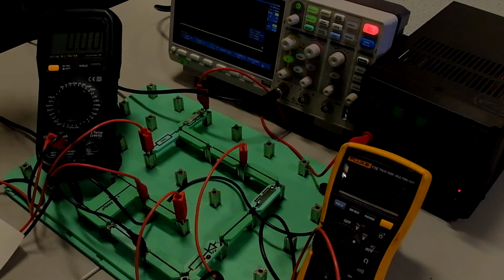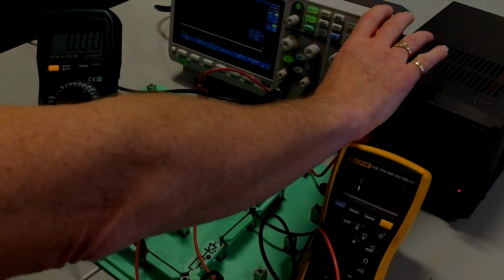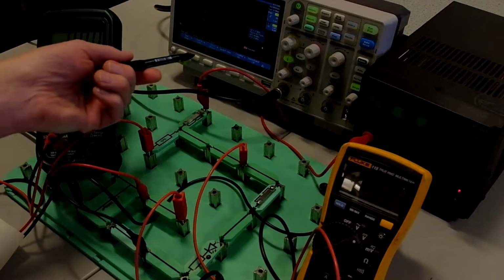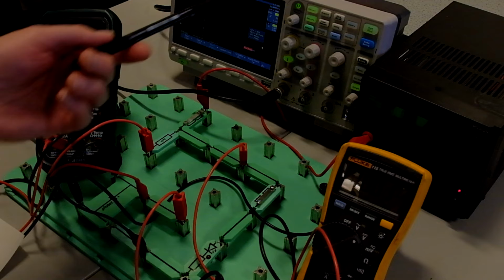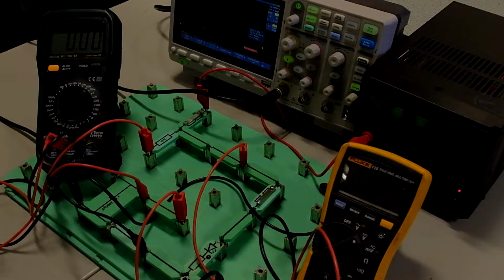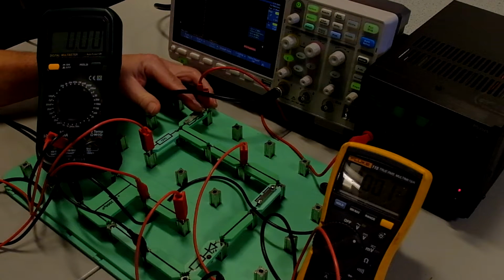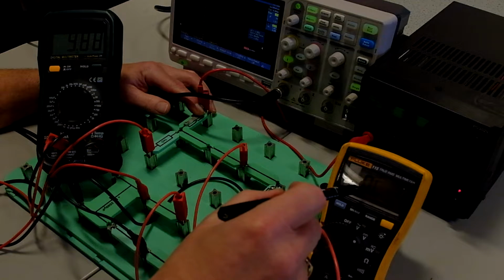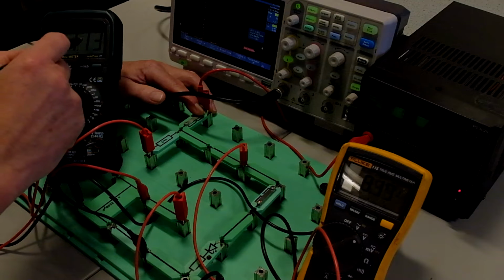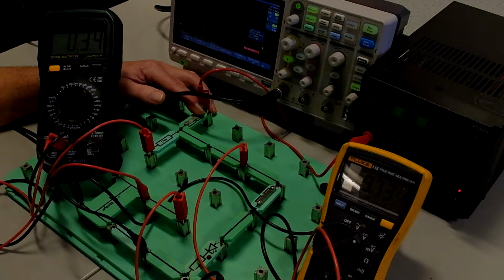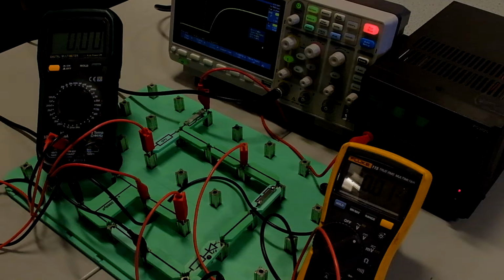What we're going to do now is capture the rising edge. We want to capture the nonlinear voltage across the capacitor on the digital scope. So we're going to put that switch on. We can see it charging up, the voltage here, and we can see the current. It started at 10 milliamps and goes down to 0 when the capacitor is fully charged. If we have triggered the oscilloscope properly, which is on a 2-second time base, we should be able to see the voltage curve. So I'll take my finger off the switch.